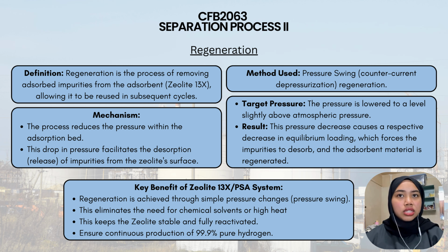Zeolite 13X systems are beneficial because pressure changes allow regeneration without any chemical solvents or high heat, keeping the zeolite 13X stable and fully reactivated, ensuring continuous production of 99.9% pure hydrogen.